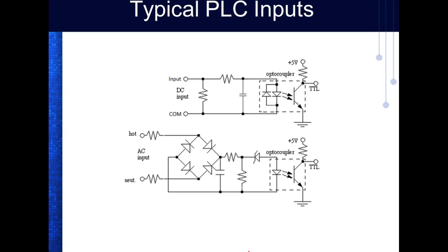You got any non-voters? So what we do is we couple, this is a solid unit. I don't know if we can get the PLC modules out, but usually if you take the module out, it's going to be a little integrated circuit. It's either going to have 4 pins on it, or it's probably going to be an odd color with 6 pins. And it's just an integrated circuit. But what it is, it's got what we call a light emitting diode on one side, and it's got a photo transistor on the other, and it's all in there together. So what we're doing is we're coupling information through light, not through electricity.